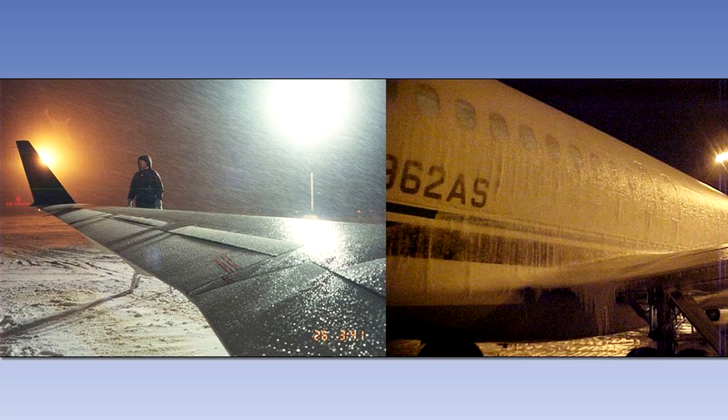The next factor that can affect the takeoff performance is contamination of the airframe. This includes the effect of airframe ice and excess water. Airframe ice will accumulate as a result of icing conditions being present at the aerodrome. These conditions could have resulted from a frost, freezing precipitation, or from a snowfall. The effect of these contaminants can be significant if they are not properly removed.